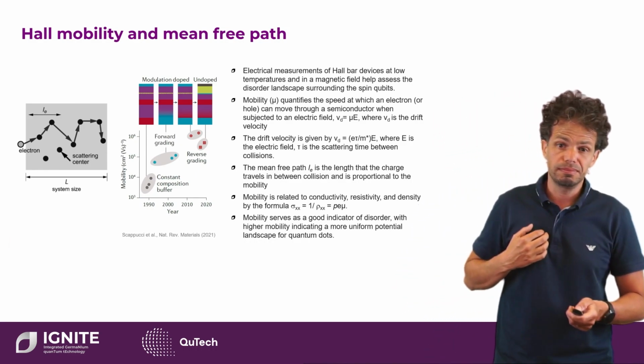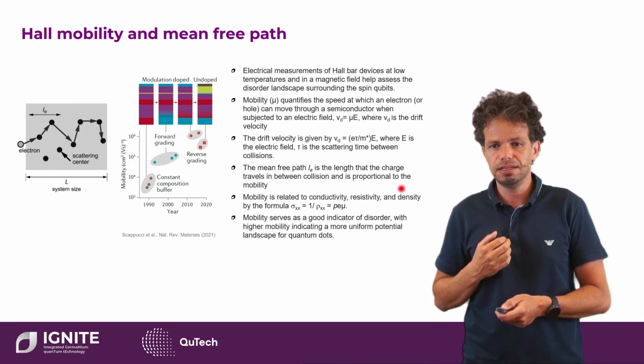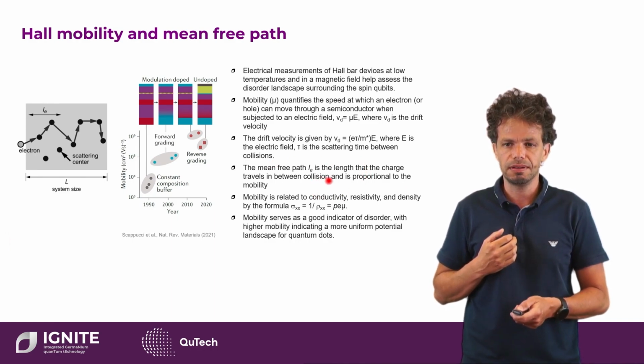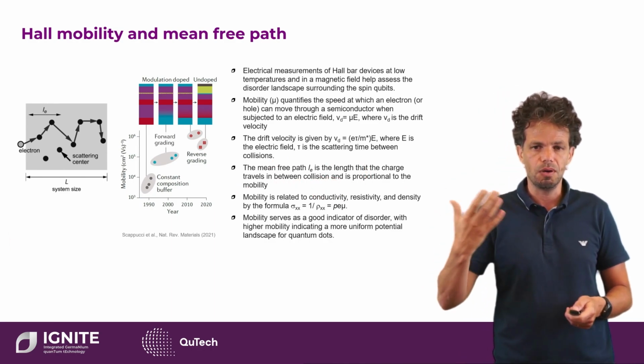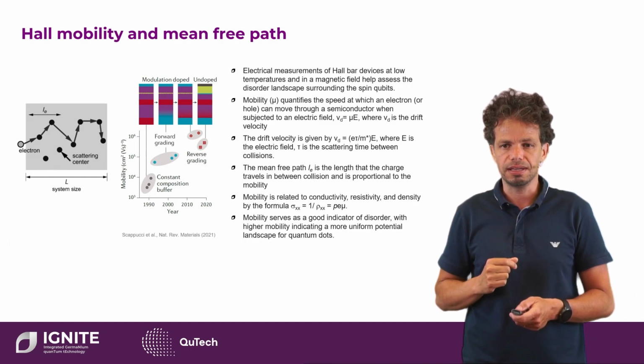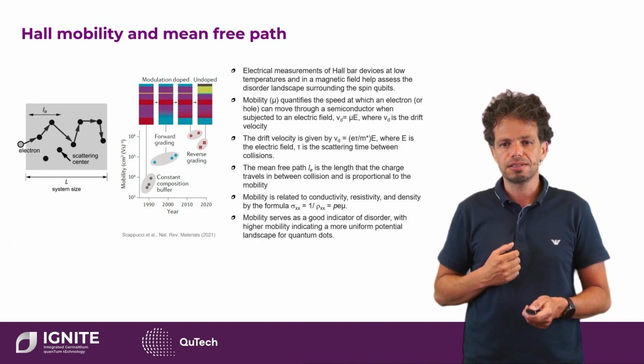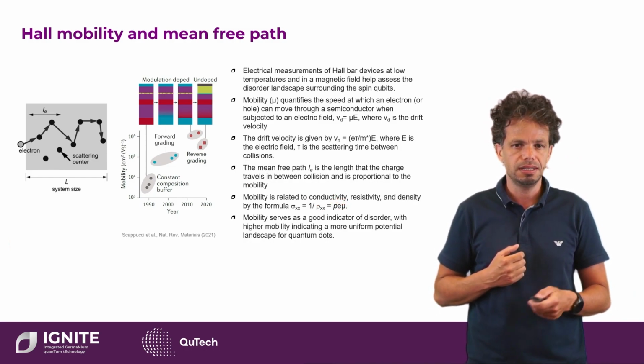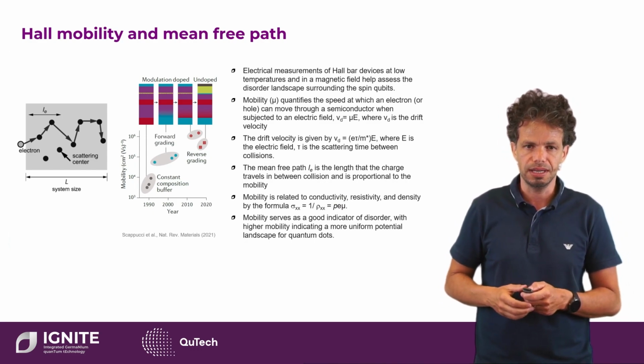Now, the interesting part is that the mobility is well related to conductivity, resistivity, and density, which are all measurable via the Hall effect, as I said before. And so you can essentially measure mobility in these two-dimensional hole gases.